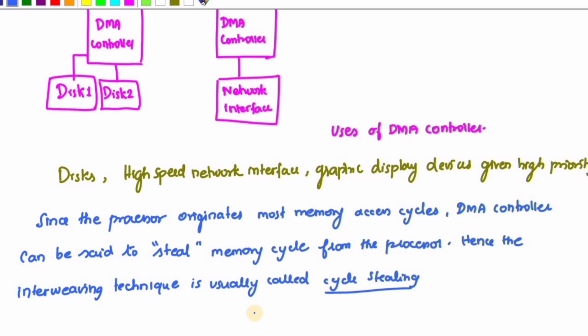Whenever the DMA transfers a block of data from the main memory to one of the disks, the program will write the address and word count information into the registers of the corresponding channel of the disk controller. It also provides the disk controller with information to identify the data for future retrieval. This DMA controller works independently to implement the specified operations.